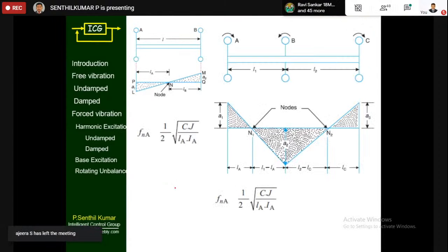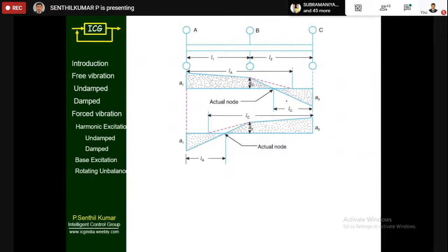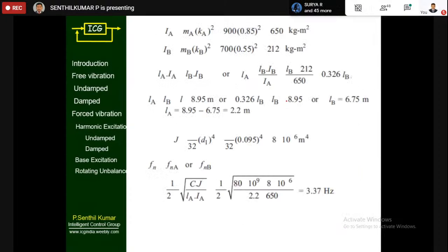Okay, so there will be questions like 2 rotor, 3 rotor. This is an example. You see what happened in 2 rotor? Only one node. So what is a node? It's a point of 0 deflection. See the deflection, 0. So I want to avoid that point. If we increase the diameter there, it won't break. But see 3 rotor, there is one deformation here, another deformation here. There are 2 nodes. So 2 rotor means 1 node, 3 rotor means 2 nodes. That question also they will ask. Based on that, you will get some problems. But this basic you must know.